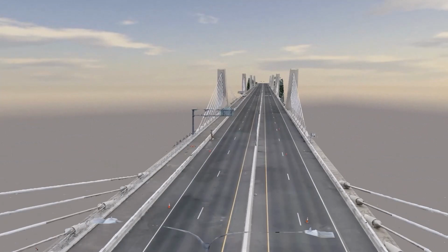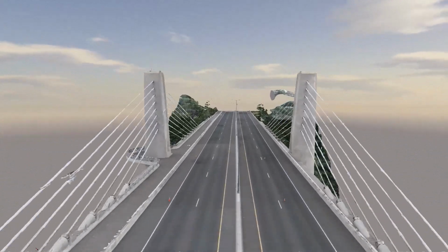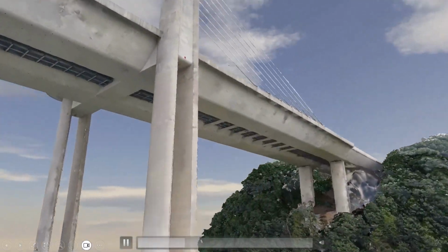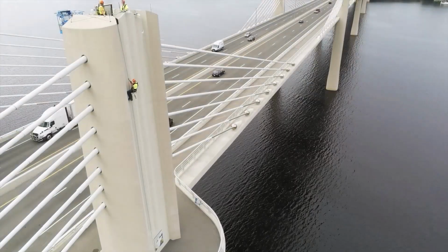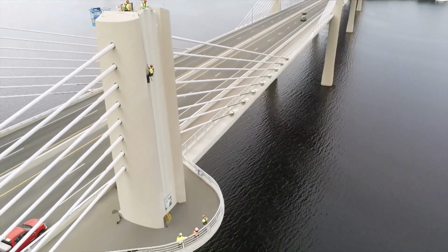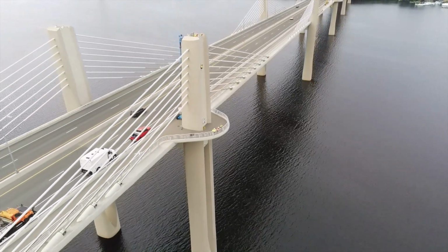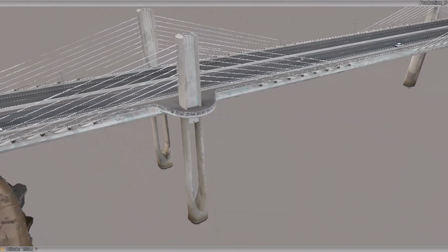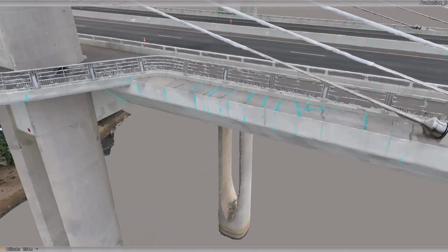So the last benefit, I guess, is just data management. Within complex structures, you might have thousands of defects that you are going to have to record. A lot of the times with traditional inspections, those defects might get generalized, with more typical annotation. When we're using a digital twin to actually do the inspection, what we're finding is that when you observe a defect, you enter it as a defect in the model, and it doesn't get lost in a summary or a generalized comment. It's actually a single defect, a single line item within the inspection.